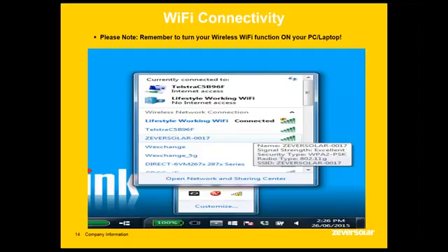This is the first step in connecting the ZeverCom to the customer's Wi-Fi. This step can be done on a PC, laptop, tablet, or smartphone. The device just needs to be able to connect to Wi-Fi. In this step, you'll need to go to the Wi-Fi settings on your device and select the ZeverSolar network. As you can see here, that's ZeverSolar 0017. However, the 4 numbers at the end may change on your ZeverCom unit. If this network is not showing, please make sure that the antenna provided has been screwed in properly and that the ZeverCom unit has been powered on through the RS485 cable.